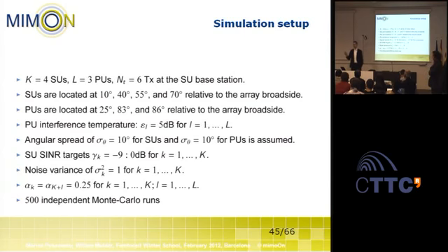Oh, but you can still have half wavelengths. I think that's not a problem. For achieving a narrow beam width, you need large apertures. If you have a narrow beam width, you are able to determine the user and primary user location, and you are able to find the nulls and boresight correctly. But if your beam is not narrow enough, you won't be able to separate the